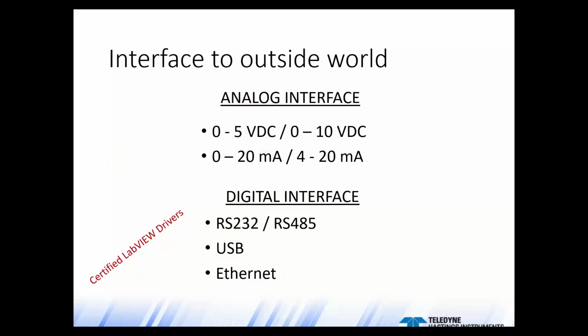You also want to give some thought to how you want to interface to the flow instrument. If you're using a strictly analog mass flow controller, you will need to send a command signal and read back the flow rate. Now, many traditional MFCs operate using 0 to 5 volt DC input-output, but we also see a lot of 4 to 20 milliamp I/O for folks with long cable runs and/or if they have connections to PLCs.